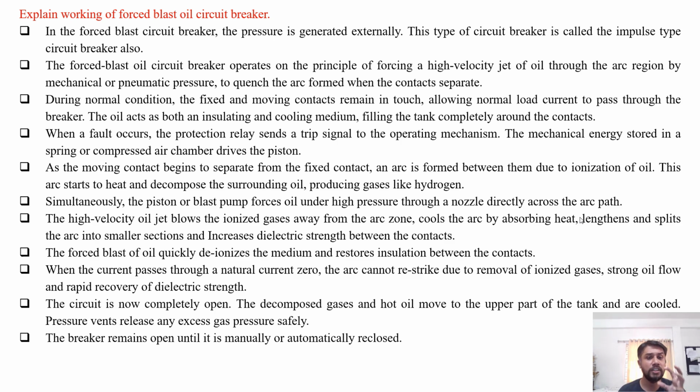The forced blast of the oil quickly deionizes the medium and restores the insulation between the contacts. Now when the current passes through a natural current zero instant, the arc cannot restrike due to the removal of the ionized particles or ionized gases, strong oil flow and rapid recovery of dielectric strength. As the rate of rise of recovery of the dielectric strength is high compared to the restriking voltage, the arc does not restrike again.